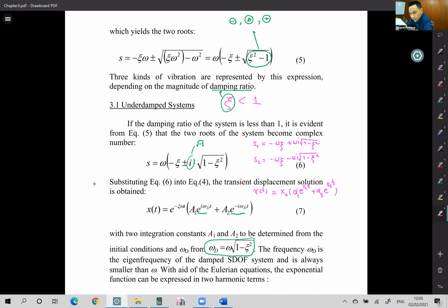Some researchers explain that the damping ratio of our building actually comes from the foundations. In the foundation there is an interaction between the soil, the footing and the piles, so they can dissipate some energy into the ground. Maybe this can be a major part of the damping, I think.